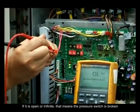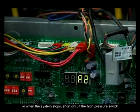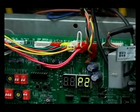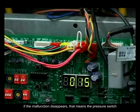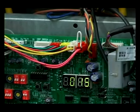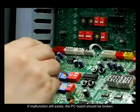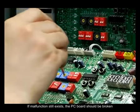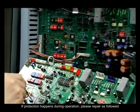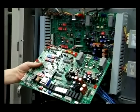If it is open or infinite, that means the pressure switch is broken. Or, when the system stops, short-circuit the low pressure switch. If the malfunction disappears, that means the pressure switch is broken and you should replace it. If the malfunction still exists, the PC board should be broken. You have to replace it with a new one. If protection happens during operation, please repair as follows.